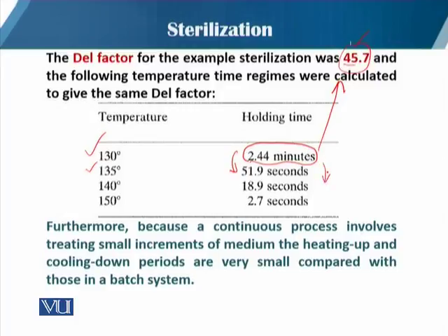If we increase the temperature by 20 degrees Celsius, from 130 to 150 degrees Celsius, the holding time falls from 164 seconds to 2.7 seconds.